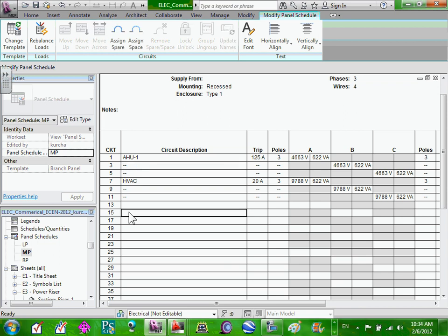If you go to a space, Ashley, if you go to a space by code, anything spare, you have to identify. If you go to a space that's nothing, you can assign a spare. By clicking here, you can assign a spare, or you can assign a space. Does anybody know the difference between a spare and a space? A spare, you need to put a circuit breaker. So I want to assign a 20 amp spare here, and a space, I want to assign just for adding later. A spare is a circuit breaker sitting there doing nothing at this moment.